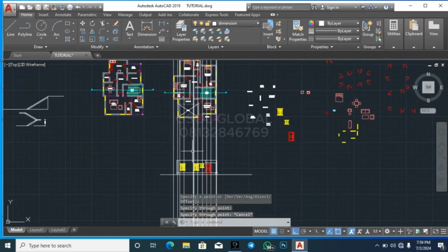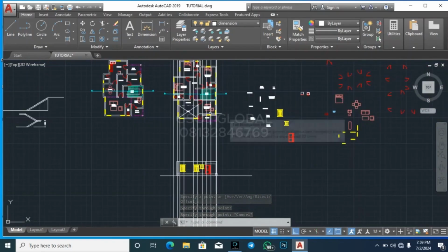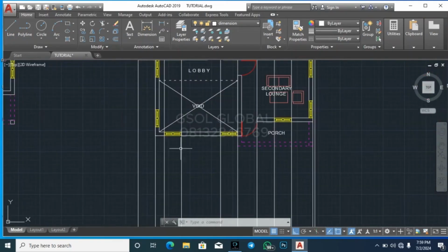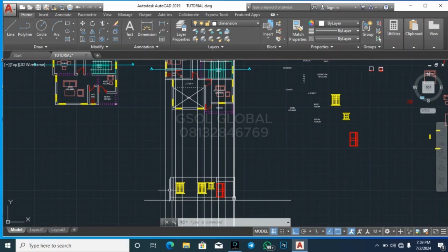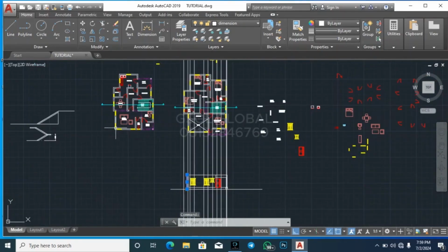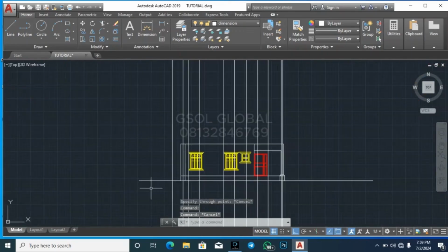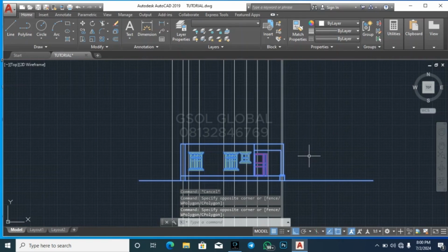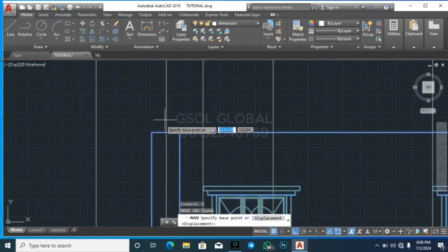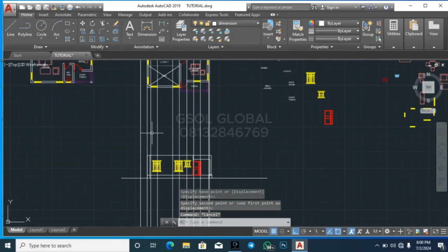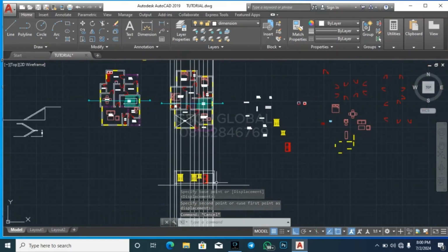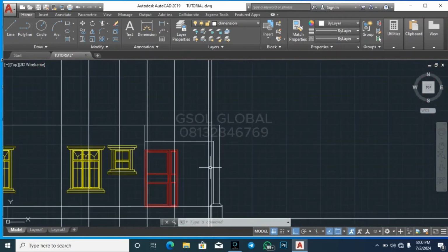Yeah. So what you will do next now is check the common points, because you need to adjust this particular ground floor to be in alignment with the first floor with a very common point. That common point is this point or the staircase region. All right. So I'm just going to use this point to just trace it. This is the wall here for this point, right? Look at it. This is the wall here. So I'm going to just click all of it, and then I will just move it to this particular line because this is the wall and this is the wall. So just drag it and put it here. You see it, right? So it's now in alignment.